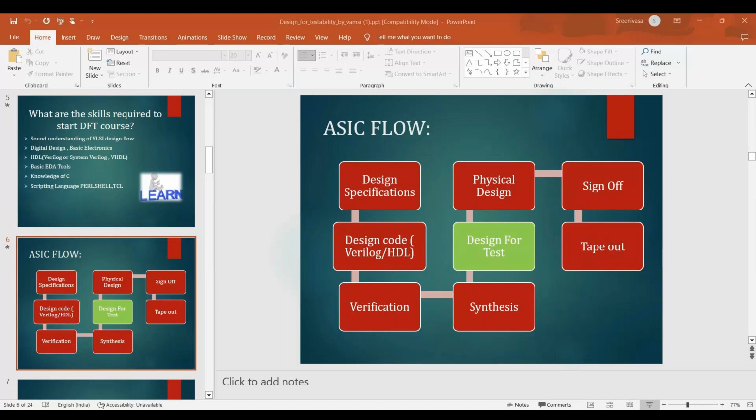So you see the right hand side diagram I have, right? What does the right hand side diagram say? For example, if you see the first one, there is a break in a net connection. What is meant by a net connection or a wire connection? A wire connection is between two elements, a gate or a flip-flop. So a break in the wire connection is a manufacturing defect. Or there is a break between multiple wire connections, or multiple wire connections became short. One wire connection and another wire connection became short, or one wire connection is broken due to corrosion effects.